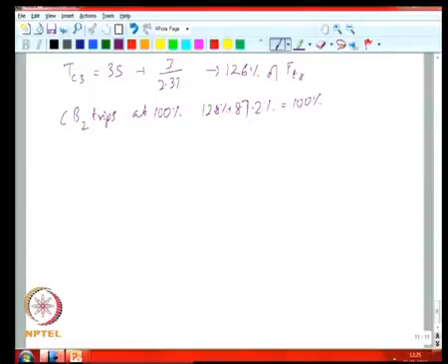If you look at the corresponding time, you get 2.1 seconds would be the time required for your breaker to trip. So, the margin that you have in this particular case is 3 seconds minus 2.1 or about 0.9 seconds of margin at the lower current level.